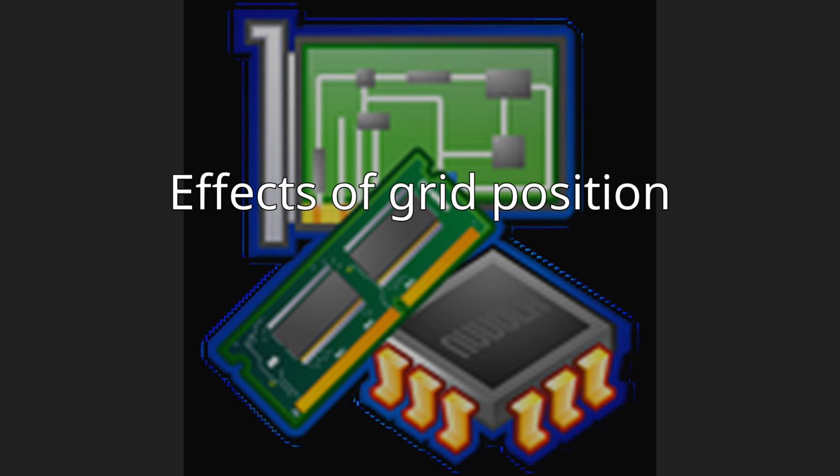This degree of amplification is referred to in valve data sheets as the amplification factor, or mu. It also results in higher transconductance, which is a measure of the anode current change versus grid voltage change. The noise figure of a valve is inversely proportional to its transconductance. Higher transconductance generally means lower noise figure. Lower noise can be very important when designing a radio or television receiver.